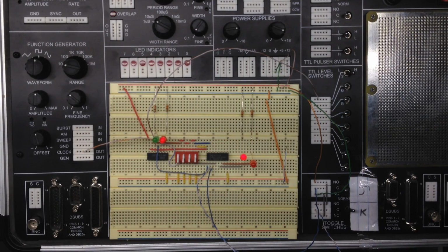The other portion of operation that we're looking for is that with a constant high on the clock, we would see the state of Q and Q naught do exactly the same as if we had a falling edge and low on J and K, where the state of Q would always stay whatever it currently is, and the state of Q naught would always stay whatever it was at the time of reaching a constant high on the clock edge.